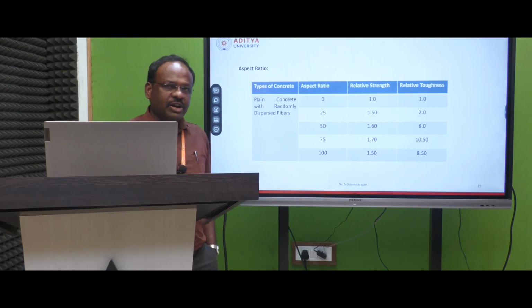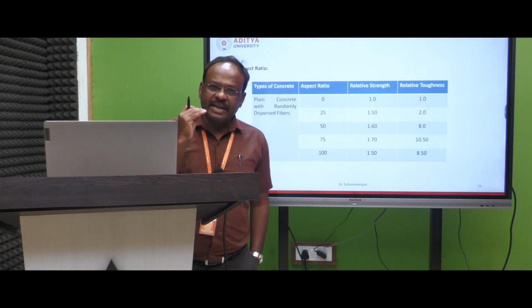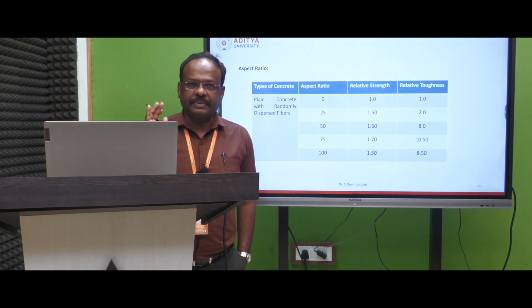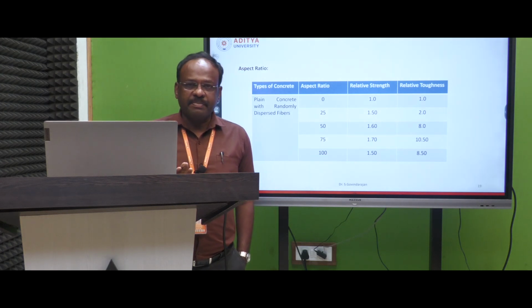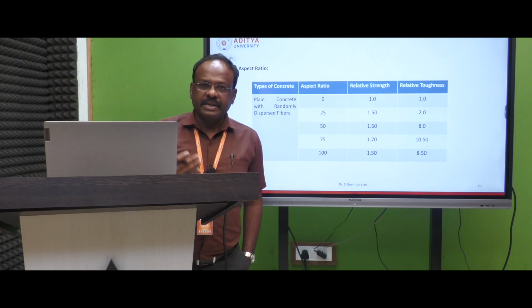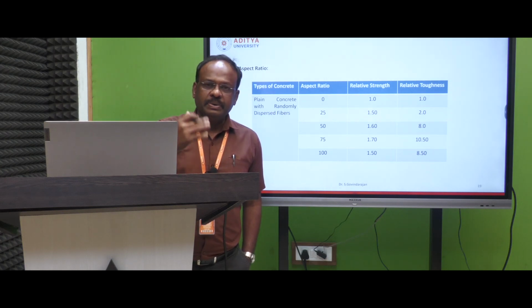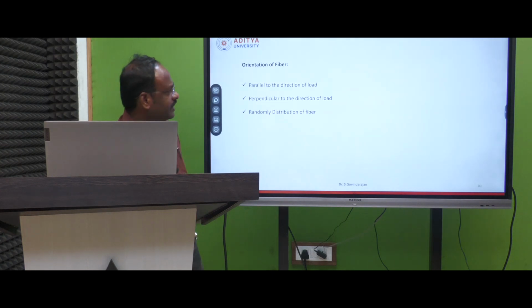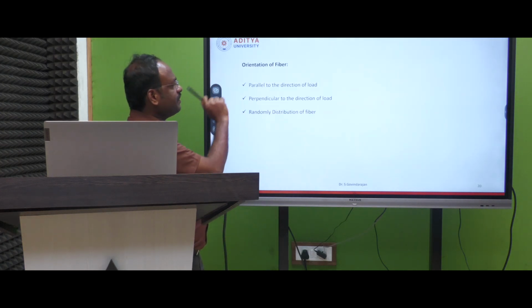Therefore the selection of aspect ratio is very important for any project using fiber, right? So again I will say, aspect ratio is nothing but the ratio of the length of the fiber to the diameter of the fiber. And the third factor is the orientation of fiber.